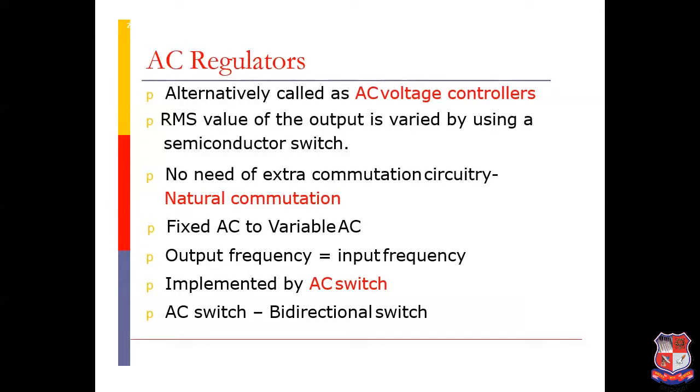Now, if we want to control speed using AC regulators, then we can achieve precise and smooth control because AC regulators use power semiconductor switches with a digital controller. The system developed using power semiconductor devices is much smaller compared to same rating of power transformer. It is to be noted that the above discussion with comparison to transformer is just to understand the requirement of AC regulators, along with some compromise in power quality.